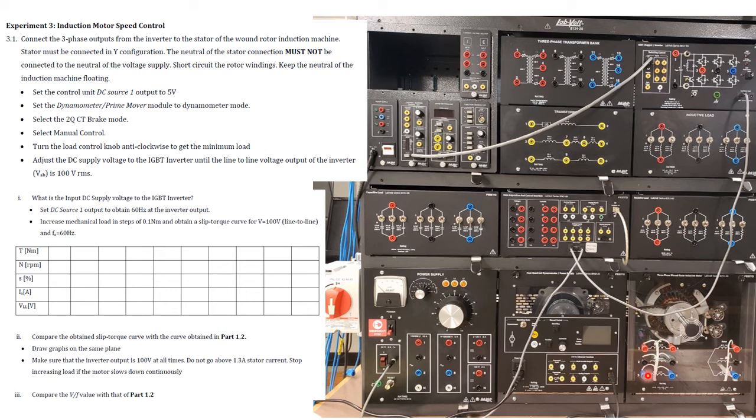In the first experiment you got this voltage directly from the voltage source, but now you should have it from the inverter. Then, like the first part, you should short the output of stator and rotor in Y connection, and this one shouldn't be connected to anything else.